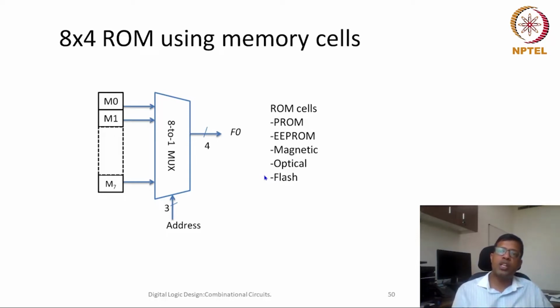Using that short circuit and open circuit analogy, a high current will pass, and if the material is of low resistance, it will burn out, so the fuse will go away and become open circuit, and otherwise it will remain short circuited. In usual operation, the current rating would be less. So it's programmable, but once programmed, you cannot change it, and that's the definition of ROM also, read-only memory.